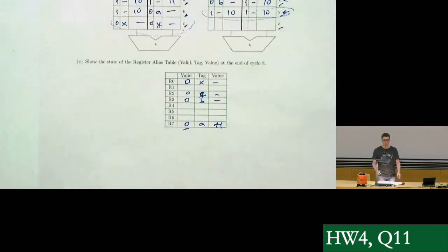Yeah. Would in this case then make sense to fill the register alias table from the bottom up based on the reservation stations? Because then we could never run into an issue where we write something in the register alias table and suddenly figure out, oh, there's a new value. Would it make sense to write it from the bottom up?